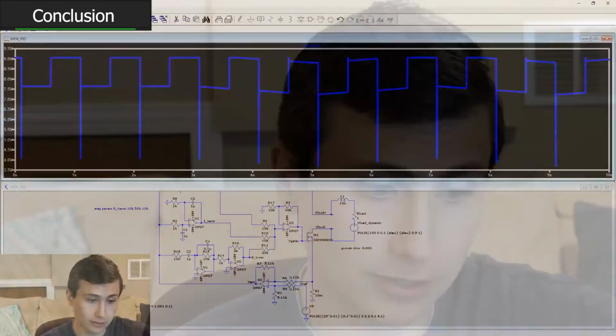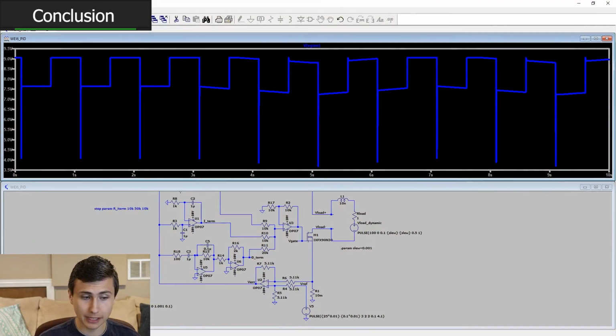Current. Until your control loop can pick up and actually figure out what's going on, there's going to be that brief moment of time where you could really vaporize that MOSFET. Oh, sorry, I wasn't showing you. Yeah, we're up at 9 volts. So you could really vaporize that MOSFET, and that's not how I would want my electronic load to work.